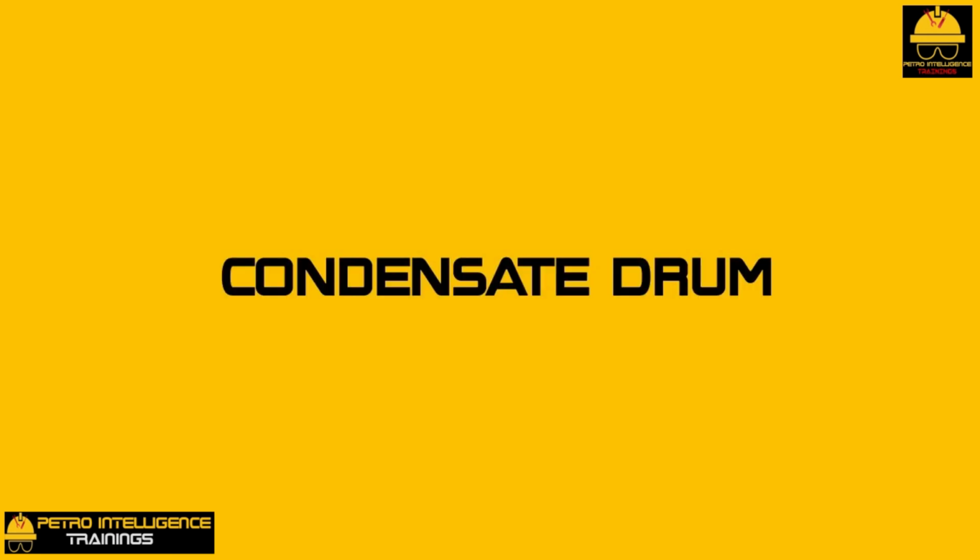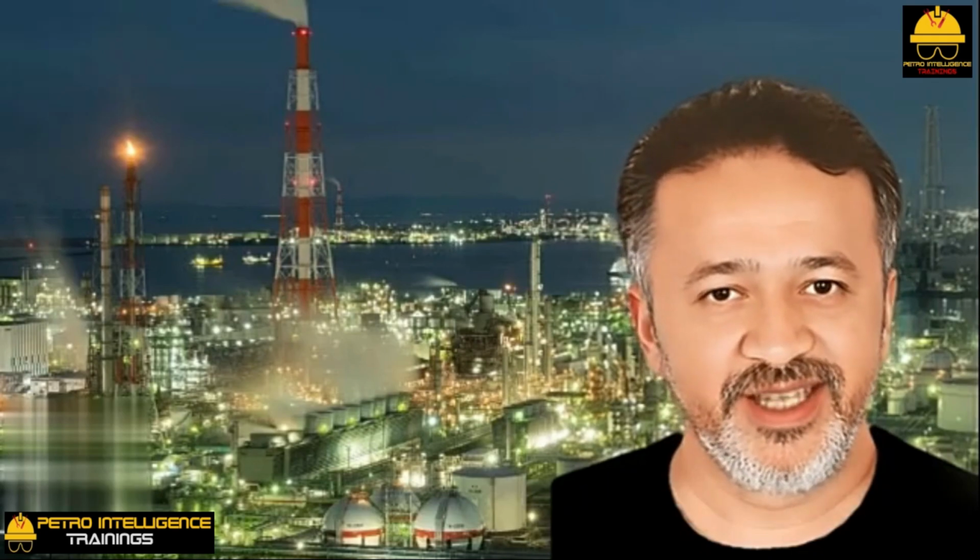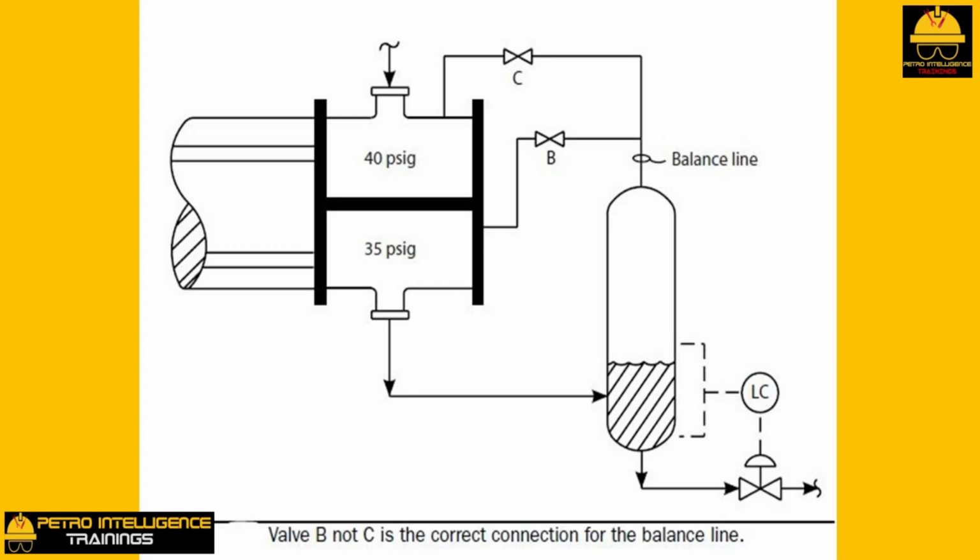Condensate drum. There is no process reason to use the condensate drum shown in this picture rather than a steam trap. In a modern refinery with large steam flows, the convention is to design systems with condensate drums for mechanical reliability. The balance line shown is required to maintain steam pressure in the condensate collection drum.